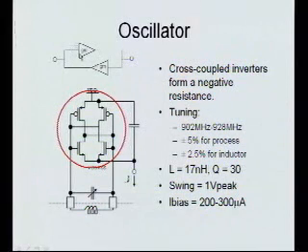So if the voltage goes up, and I'll wave my hands, if you do this with the voltage, this will actually suck more current from this side. So it'll actually pull current the opposite direction from a normal resistor. And so it acts essentially like a negative resistance. And so the key is, if the negative resistance is stronger than any real resistance there, then you're unstable, and you will automatically try to lock up.